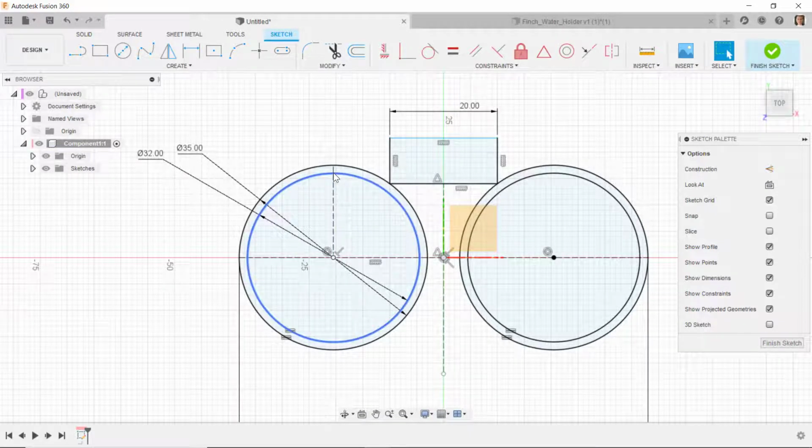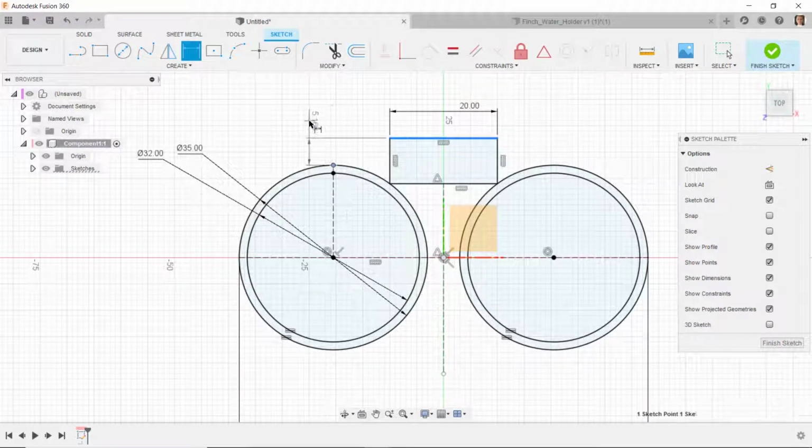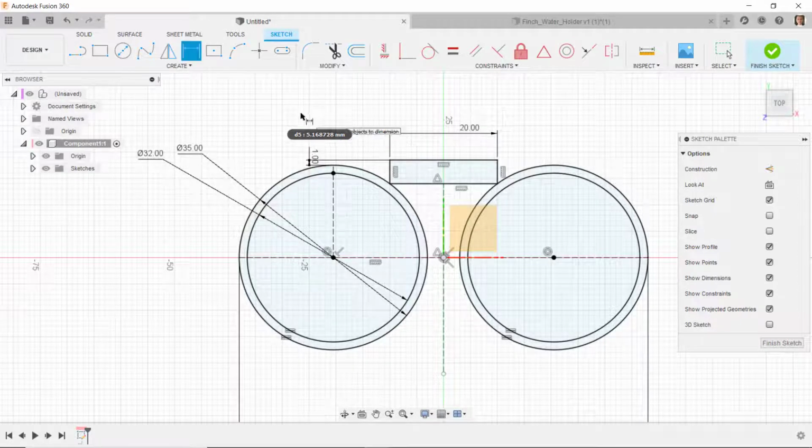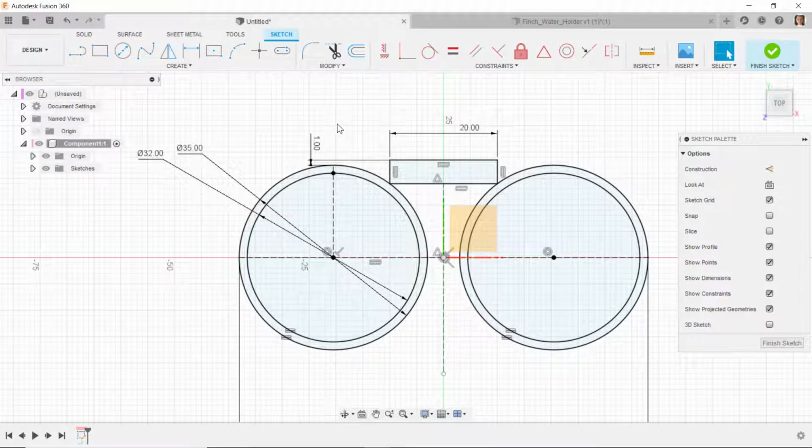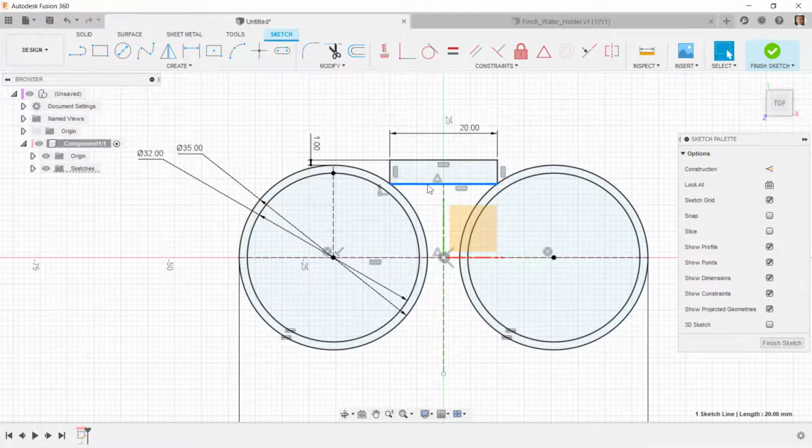If I were going to measure it from there, I would go ahead and put a sketch point at that location. So I do the measurement with my calipers, and I measure from here to here, and I get that as a distance of 1 millimeters. Of course, if you measure that and it's actually 1.5, you know, whatever it is, you can edit the sketch to change it to the dimension that it actually is. I'll change this line to construction line.